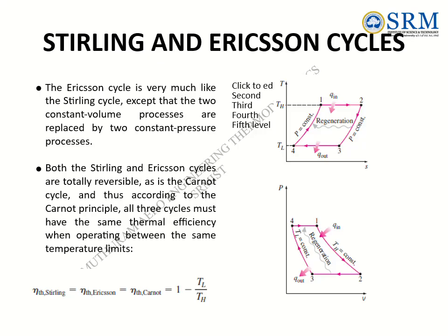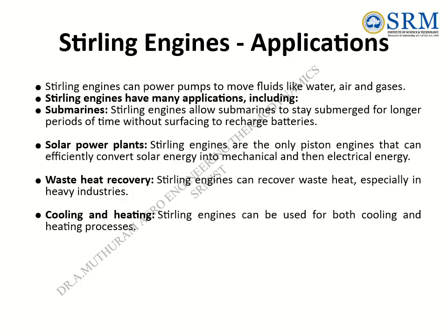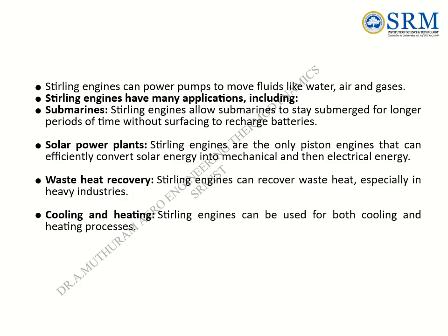The Ericsson cycle is very much like the Stirling cycle, except that the two constant volume processes are replaced by two constant pressure processes. Both the Stirling and Ericsson cycles are totally reversible, as is the Carnot cycle, and thus according to the Carnot principle, all three cycles must have the same thermal efficiency when operating between the same temperature limits. Stirling engines can power pumps to move fluids like water, air, and gases.